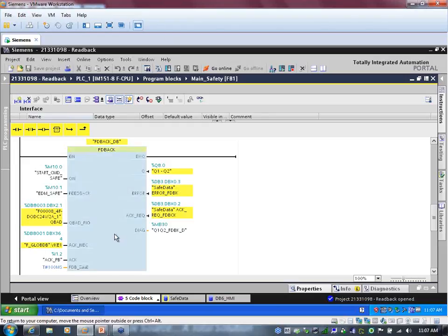So it's monitoring all the time. This Q bad input is the QBAD. There are bits associated with the status of channels and the failsafe within the failsafe modules that will allow you to determine which channel went bad. This feedback block uses it so that, should the module fail, you're not going to need an acknowledgement of this particular function block. That's all that's doing there.